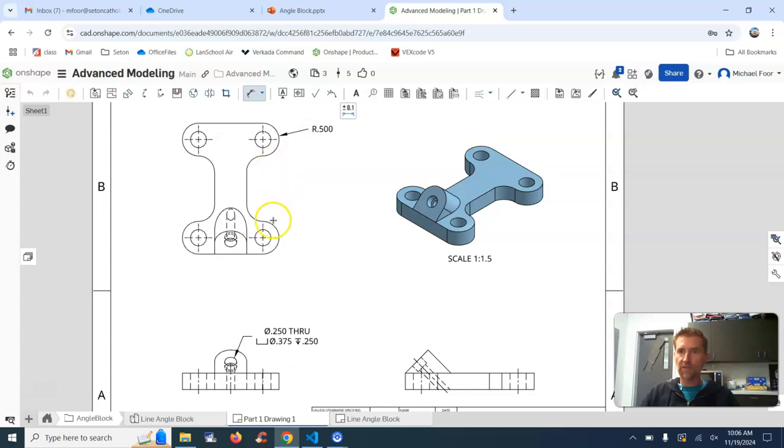So let's just start adding some dimensions. And put in those big circles. I'm going to go from these centers here, so I want to know that is in the center. Now, it is okay to put dimensions nested inside of others. Okay, that would be better. We don't like to have crossing edges like that. That we don't like to do. So it's okay to nest them inside each other. We just want to make sure they stay kind of organized.